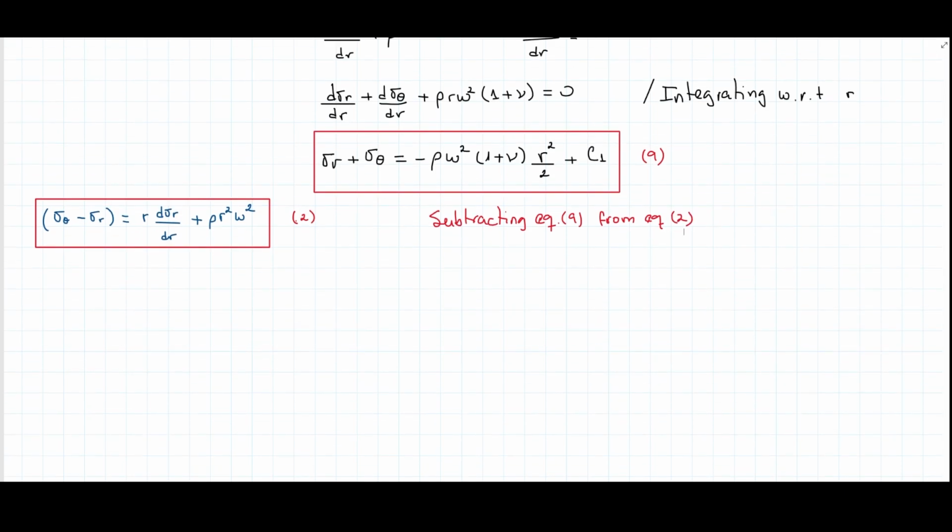So let's first subtract these to the left side. So this one and this one. So what's going to be? It's going to be here, sigma r plus sigma circumferential stress. Then minus this one here, which is circumferential stress, plus radial stress. And that's going to be equal to what? Well, to all of this minus all of this. As simple as that.